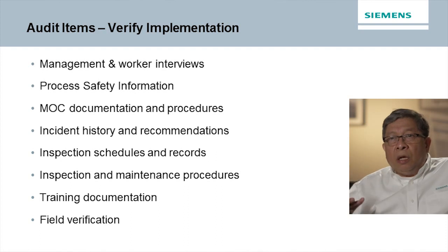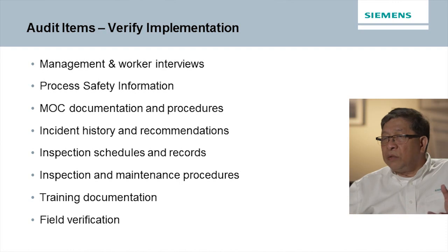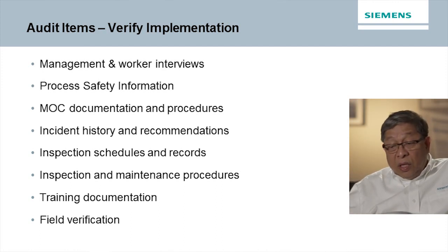I mentioned earlier, or maybe I haven't mentioned, that, for example, we have a lot of ISO drawings, right? In the small plant where I worked, I had over 10,000 ISO drawings, and if I had to do an inspection based on those ISO drawings, I'd never get it done. So I know some people are doing what other companies are doing, which is actually circuitizing them. If I have a pipe run, for example, from my stores all the way to the top of the tower, I can have maybe 20 ISO drawings, but actually the service conditions and material of construction are the same. So why do I need to send my inspector 20 times to inspect each ISO fab drawing when I can actually consolidate that as one inspection package? So those things, why we're not complying, why implementation is struggling, we can investigate, validate and verify. And again, those things help us identify opportunities for improvement.